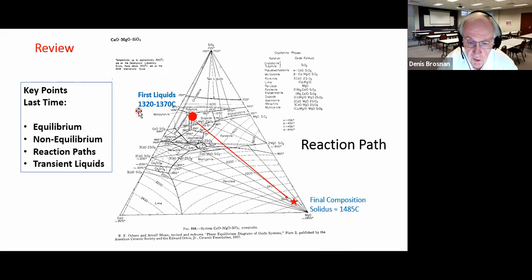But nevertheless, when we use lime as a flux, the first liquid occurs at about 1320 to 1370 degrees Celsius. So there is a formation of melted phase within the product on preheating. When you're heating up at about 1320, it can be lower than that with alkalis present. I understand that. It's dependent on the overall composition.